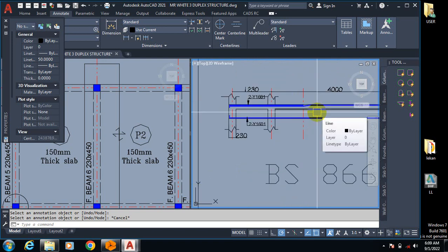And then you're overlapping at your tension zone, you're overlapping at your compression zone. There are values for them. For your tension, it is 40 times the diameter of the reinforcement. Then for your compression, I hope I'm right.